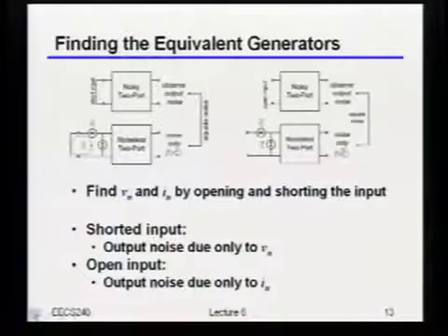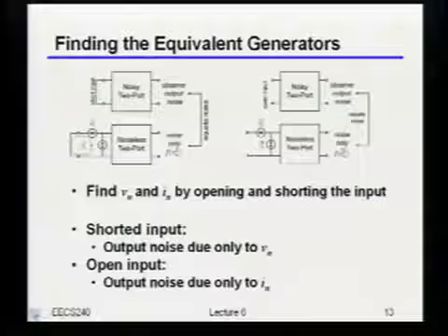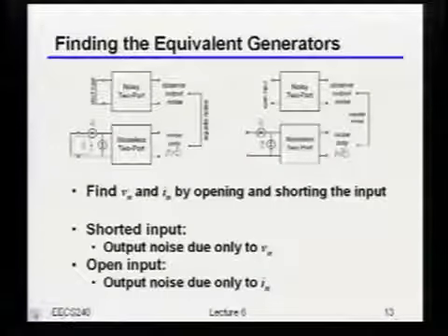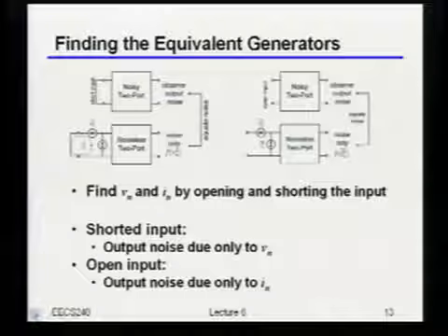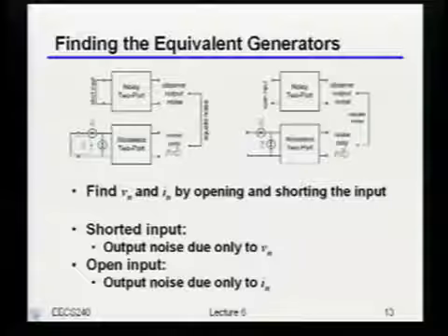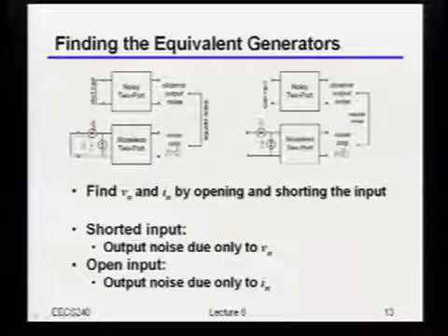So last time, as you guys may remember, we were talking a little bit about input equivalent noise generators, which usually are useful from a spectral density standpoint. Because if I have some general purpose op amp and I'm not sure how I'm going to hook the thing up, I want a fairly simple way to characterize its noise performance. So we said that since many op amps have a non-infinite input impedance, we need to model both the input equivalent voltage noise generator as well as the current noise generator.